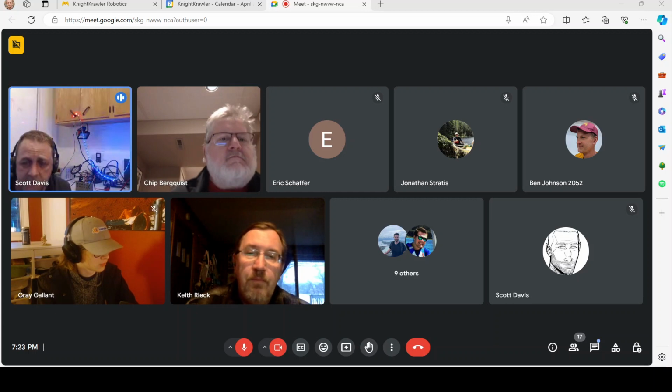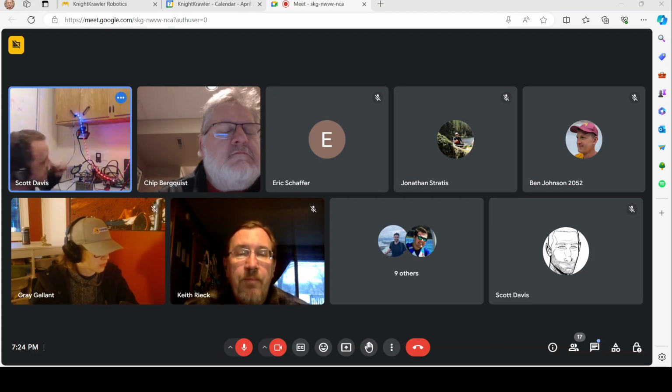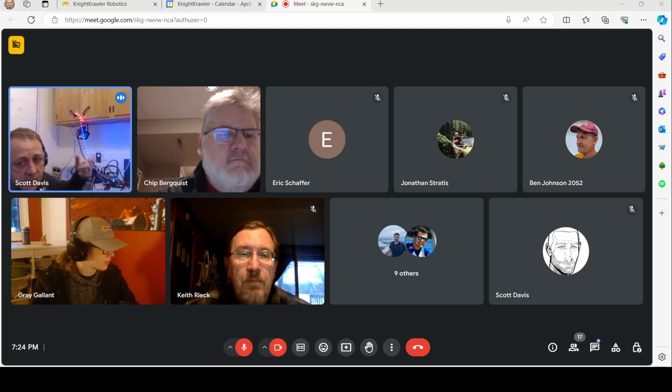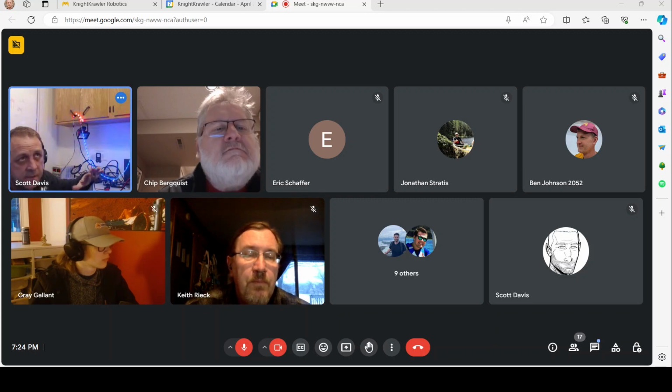So we use a library called Fast LED. There's actually quite a few different LED libraries out there, but we use Fast LED. If I remember watching Afomia do this, we were moving a 3 or 4 block pattern down the strip. And then on every cycle, which I think was 10 or 20 milliseconds, it would fade all the pixels that had been lit up by 10%.